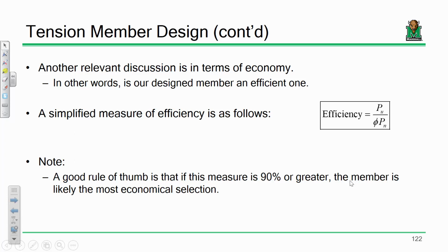So if we're talking about tension members and braces in buildings, it stands to reason that you would have some sort of depth limitation, because you're going to fit that in a wall or in an elevator shaft or somewhere in the building, and it can't be 30-some inches deep or whatnot. So putting a limit like, oh, it's a W12, or oh, it's a W10, is probably a pretty reasonable limit.